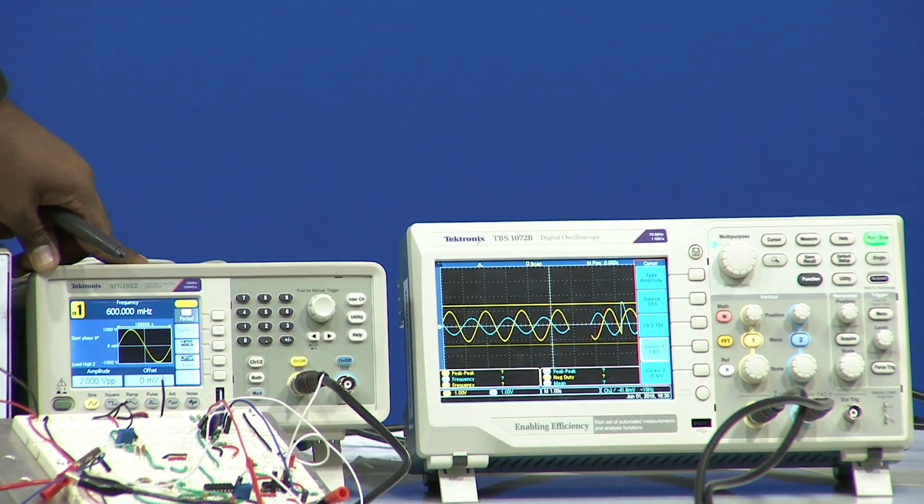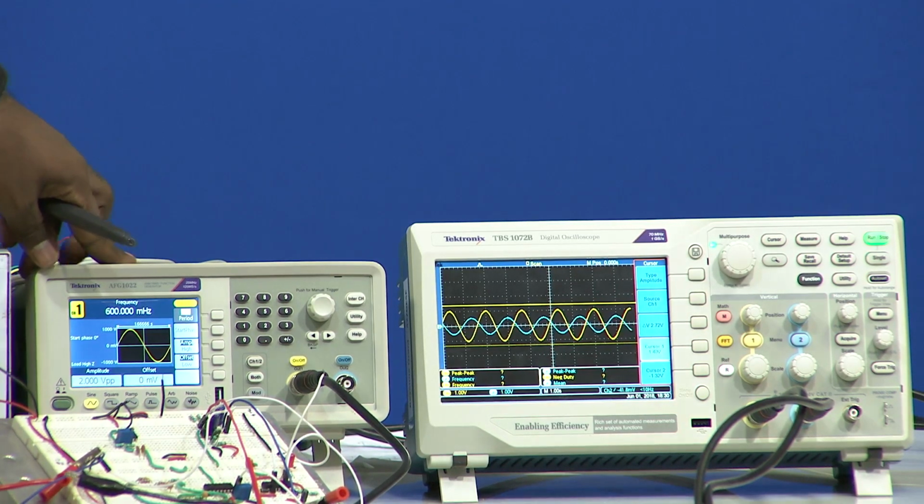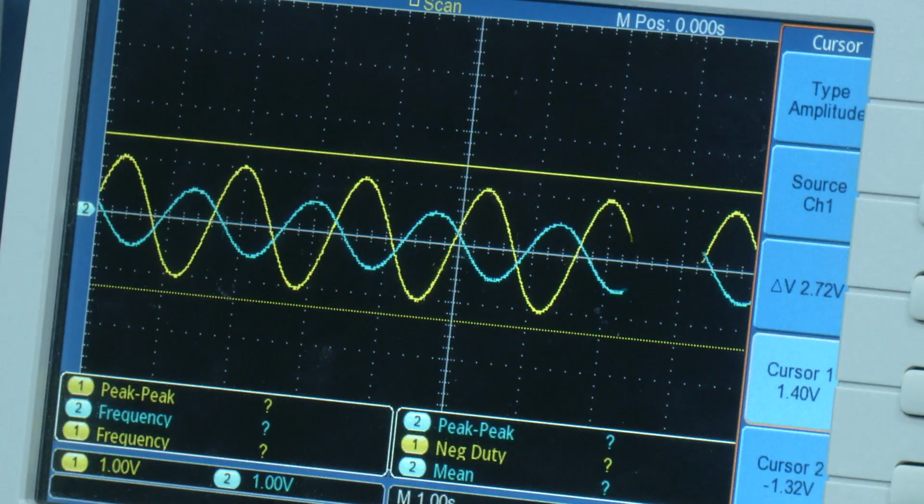below the cutoff frequency, the amplitude will be attenuated. It will not be completely removed, but the amplitude will be attenuated from the cutoff frequency. And one more thing we can understand is that since it is a second order filter, we can see the drastic change when we are decreasing from 1 hertz.